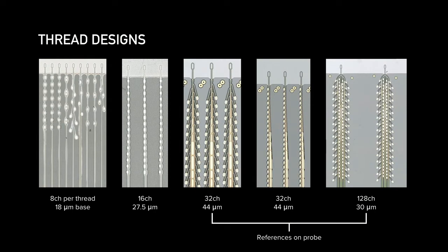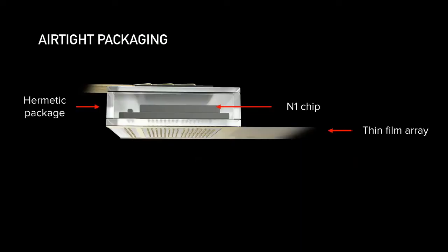We've been able to do this by adding layers and reducing the sizes of the wires down to as small as 350 nanometers. This is less than the wavelength of visible light. Because we're using a lithographic process, essentially if we can draw it, we can also make it. So on one end of our probes are the electrodes. On the other end is where we connect the probes to the electronics, through conductive feed-throughs. This substrate is part of the hermetic electronics package.